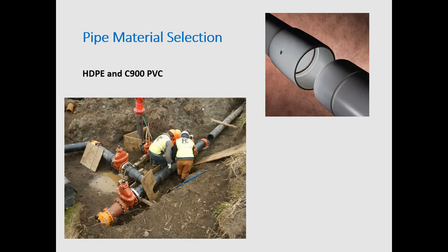So, pipe material selection. HDPE for the design build. That's how it was decided. For the design bid build, knowing that we were going through some of these petroleum contaminated areas, there's the risk of using HDPE in these areas. It's not just risk, it's just not recommended, period. So through the early stages of design, we recommended, and they don't want to use metallic pipe out there, too corrosive of soil. While it's a better product for contaminated areas, they didn't want to do it.